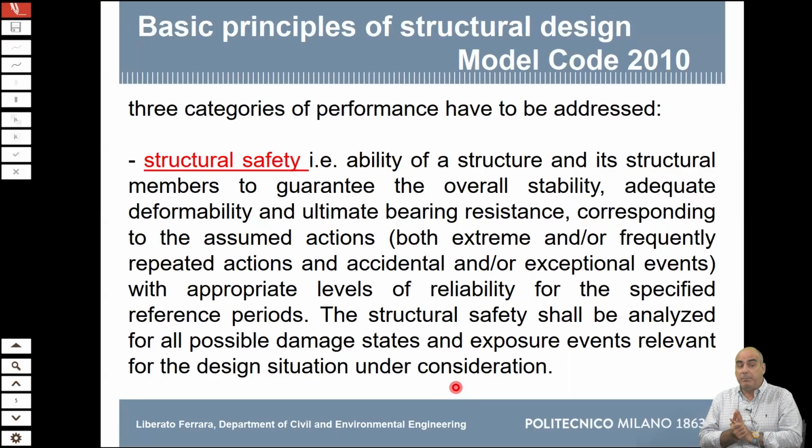Serviceability limit state, the probability of failure that we accept, the probability of reaching that limit state, is on the order of 10 to minus 3, much higher. That's true. It's something that happens frequently. Most likely the actions that we expect for those states are lower. And so we got it.